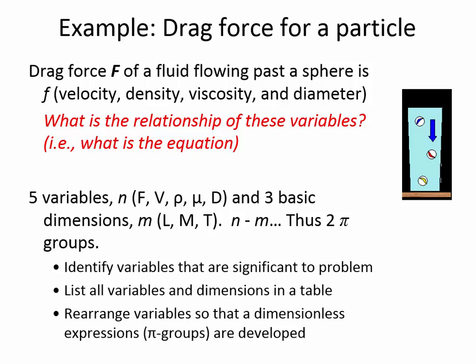This grouping: density, diameter cubed. Now, it doesn't do anything with this next row, velocity divided by diameter, so it stays the same. I haven't done any combinations because it only has units of time right now, and I'm not canceling out time. Right now, I'm trying to cancel out mass.